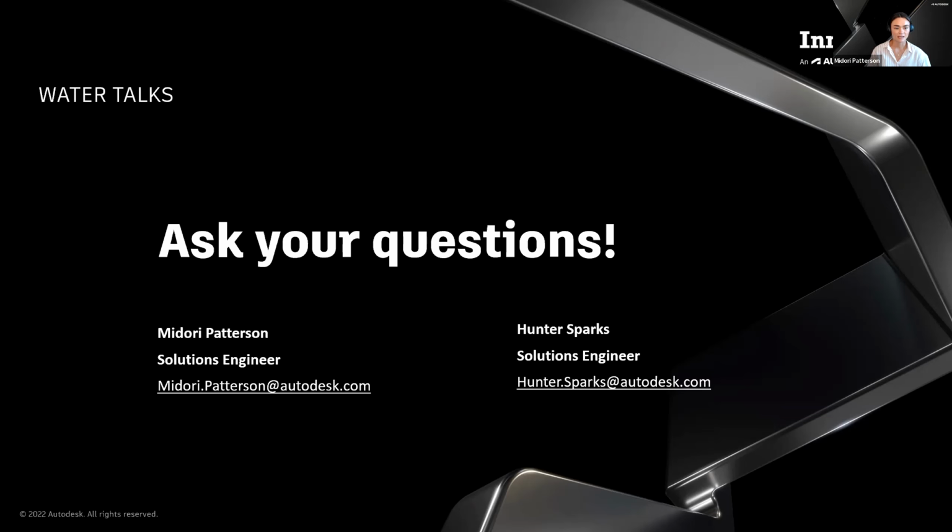Yeah, and then the next question is, are InfoDrainage and InfoWorks ICM interchangeable? There is a routine within InfoWorks ICM to load a pipe network from InfoDrainage. It would just import the geometric properties of that pipe network. It doesn't necessarily save the InfoDrainage model results, but basically adds the InfoDrainage pipe network to your InfoWorks ICM model that you can then run in ICM.